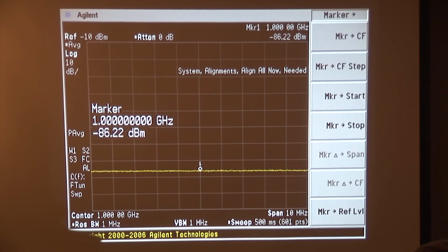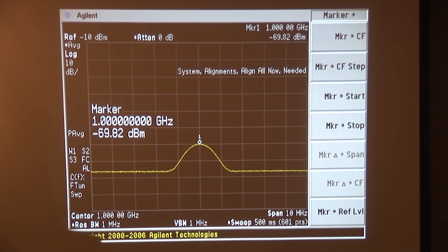Now, I haven't touched the vector signal generator except to turn off the signal it was transmitting. Now I'm going to turn it on, and where before we had a 3 dB signal to noise ratio, now we'll see what the new signal to noise ratio is. RF on. We'll hope we see it. And now we're seeing a signal to noise ratio that's equal to about 16 dB. Okay, and I didn't have time to really go through this myself before the talk, so I'm going through this with you.